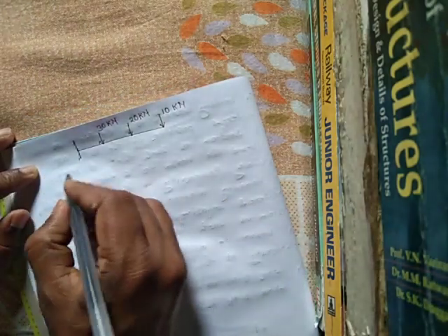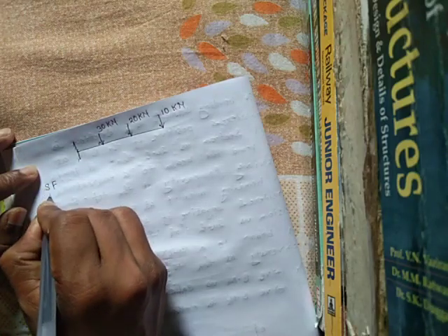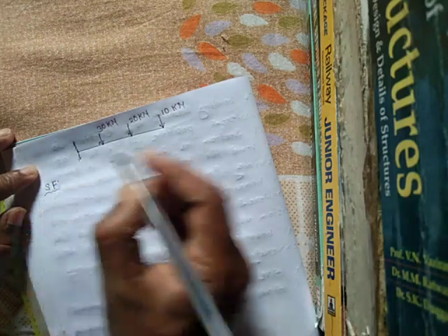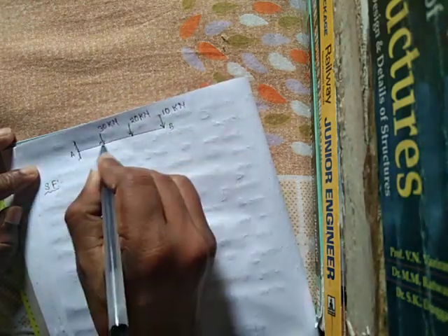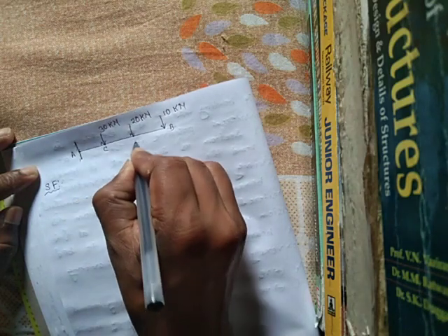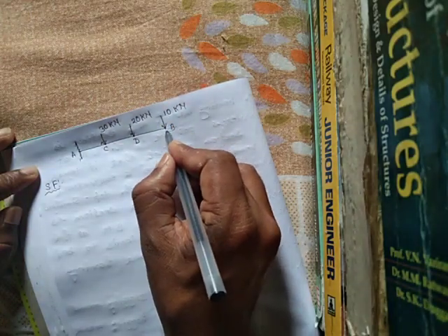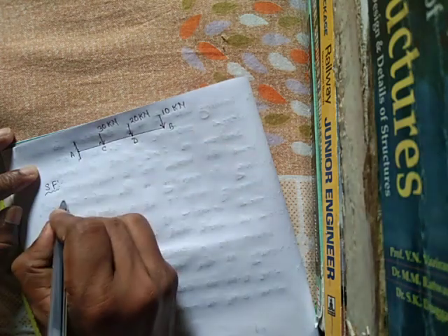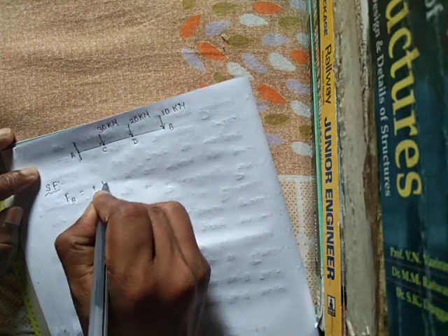Now find out the shear force. Then we will easily draw the shear force diagram of that beam. Say this is point A and this is point B. In between A and B, I have chosen the points C and D. At point B, the shear force is the total load at point B, which is 10 kilonewton. The shear force at point B is equal to plus 10 kilonewton downward.